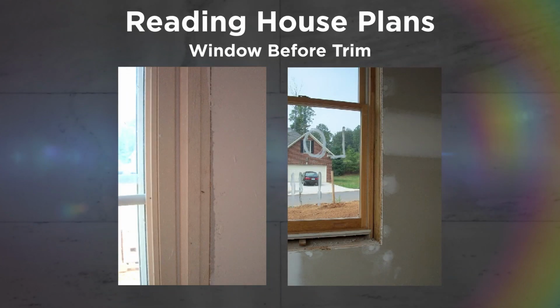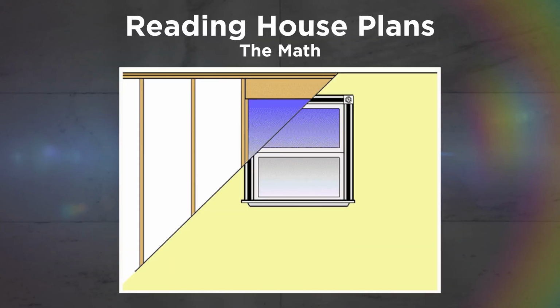Here are two examples of the window installed before trim is added. Notice a slight gap between the jamb of the window and the rough opening. Kitchen and bath designers often make a mistake when reviewing a house plan and calculating window and door sizes. They assume the dimensions on the house plan will be the finished dimensions on their kitchen or bath plan. As this illustration shows, that will not be the case.